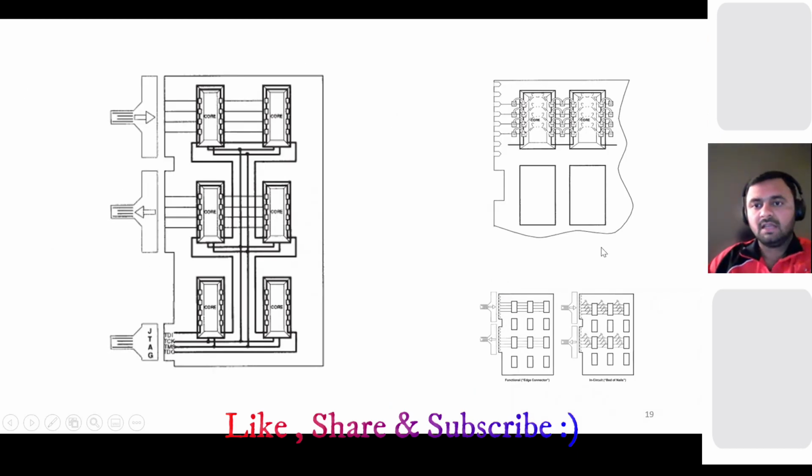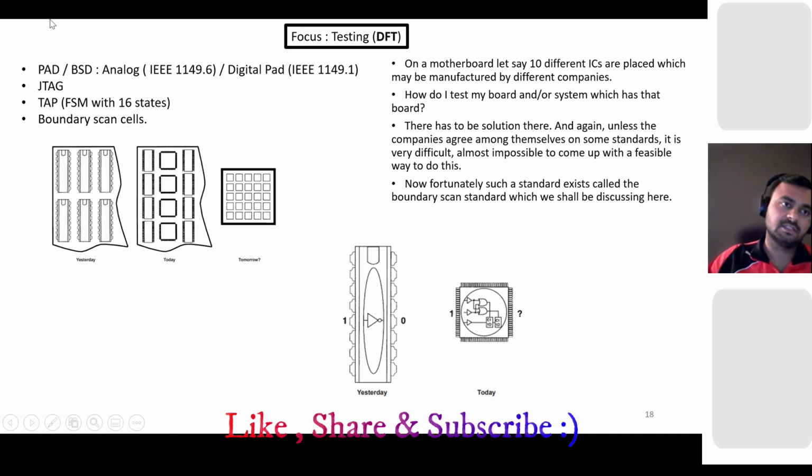Yeah, so here you can see. Earlier we were using this in-circuit tester, or bed of nails, where you connect all the signals physically to a nail-like structure and you test the signals there. But now it's very difficult. You don't have that access anymore. So now you need to develop some mechanism to test that. That's why this JTAG, the Joint Test Action Group, was formed, and they came up with this standard to test those boundaries. Boundaries means outer logic.